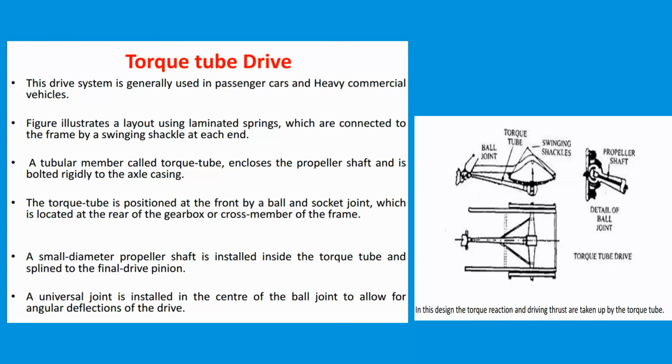In most applications, the drive shaft uses a single universal joint, which has the disadvantage that it causes speed fluctuation in the drive shaft when the shaft is not at a straight position. The Hotchkiss drive uses two universal joints, which has the effect of cancelling the speed fluctuation and gives a constant speed even when the shaft is no longer straight.